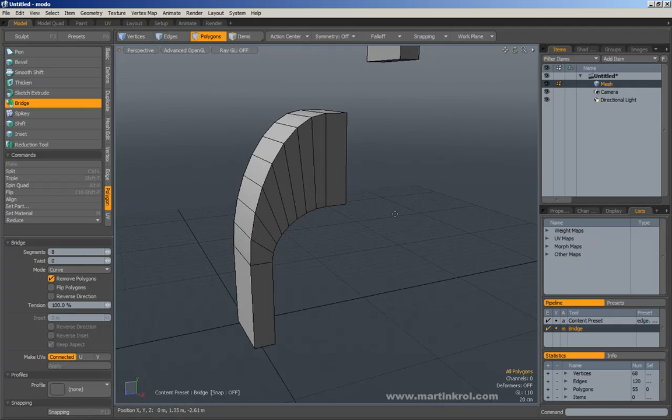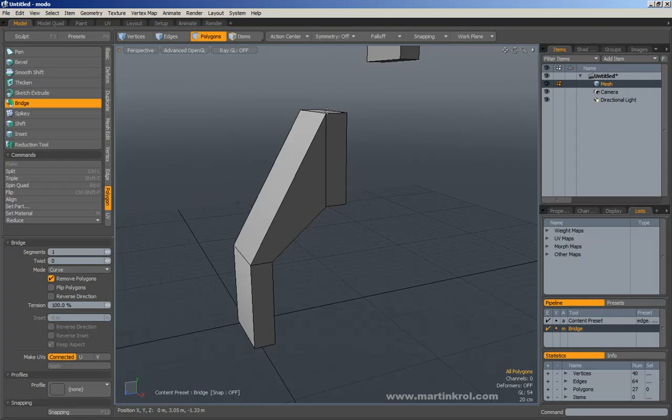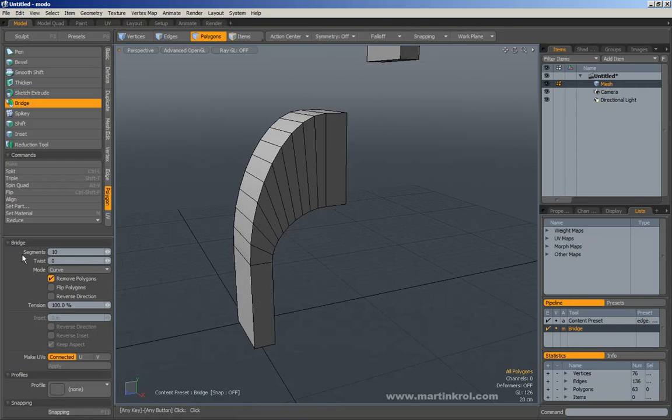Now, if I left click on my viewport and move my mouse, you'll notice that I can increase or decrease the amount of segments that are being used to blend between those two polygons. So I can just make it a completely linear connection, or I can left click and drag and make it a much smoother transition. Now, the thing that changes the amount here is the segments. So I can actually go into the interface over here. I can left click and increase or decrease the value here, or I can just type in whatever number I want. So let's just say I want 5, that'll do.